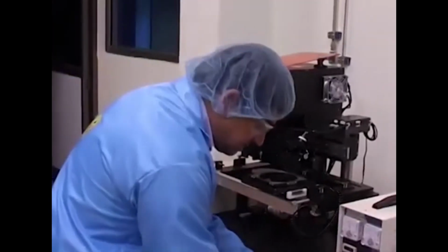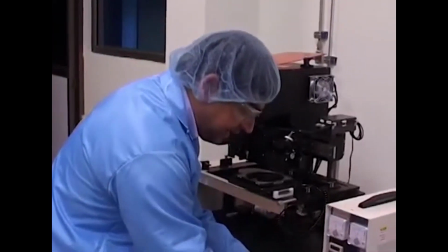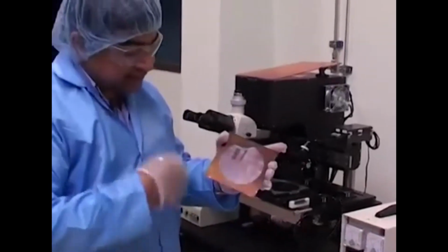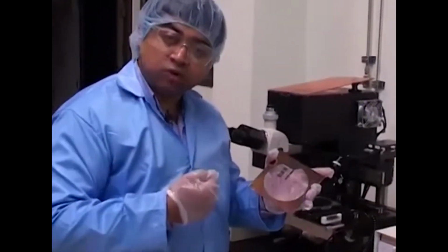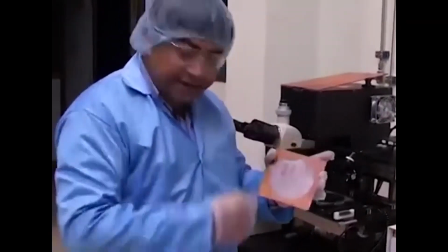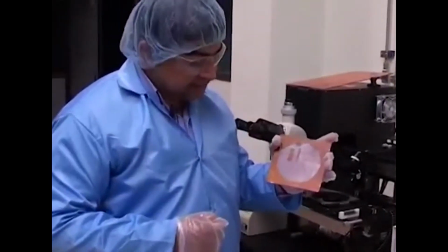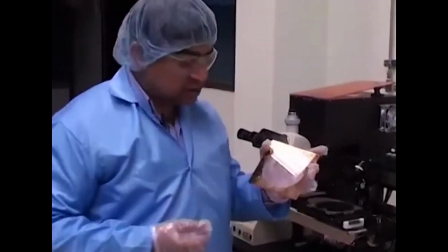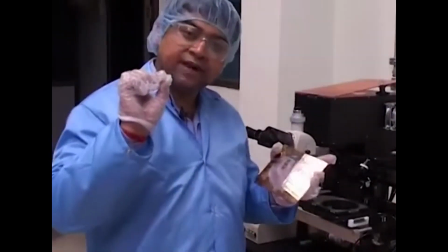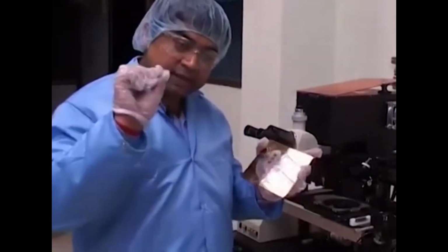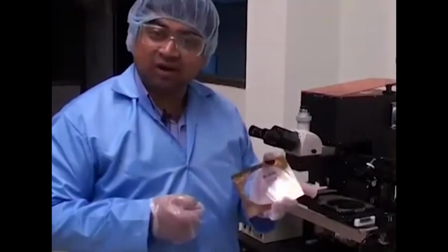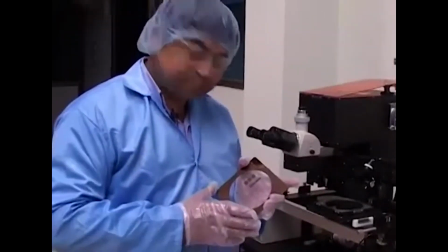So you take the hard mask, and this has to be pre-cleaned. This of course is a pre-cleaned sample. What you should normally do is use compressed nitrogen or compressed air and blow dry it thoroughly, so that there are no marks. Suppose there is some finger mark on the top, you could use a small amount of acetone to wet a Kim wipe, slowly rub over it, then wash it in ethanol, and then clean it using dry nitrogen or compressed air.